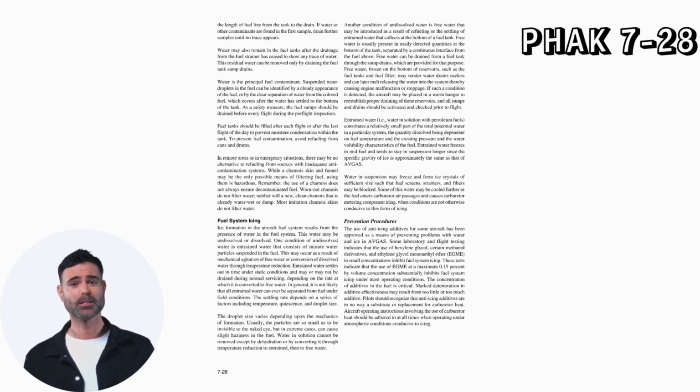Suspended water droplets in the fuel can be identified by a cloudy appearance of the fuel or by the clear separation of water from the colored fuel, which occurs after the water has settled to the bottom of the tank. As a safety measure, the fuel sumps should be drained before every flight during the pre-flight inspection.